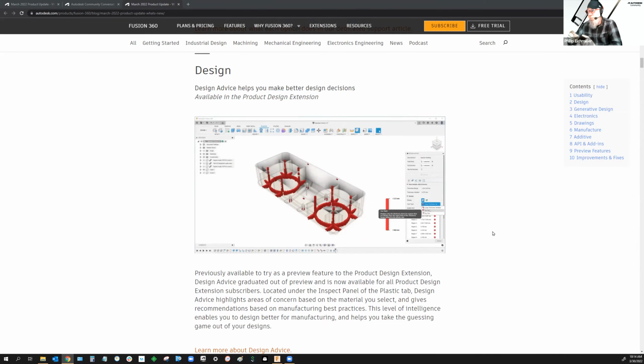But when you go over to plastics design, almost none of it is centered around the fabrication process. I see this with my students all the time, we'd be working on plastic parts and they'd have unrealistic thicknesses between the shell and the ribs. They would have ribs that were 0.5 millimeter wide, which is never going to work. Plastics design in Inventor and Fusion has for years allowed you to get all the way to the part where you're making tooling, and a plastics engineer sits and looks at your product and says, you have to redesign the entire thing.